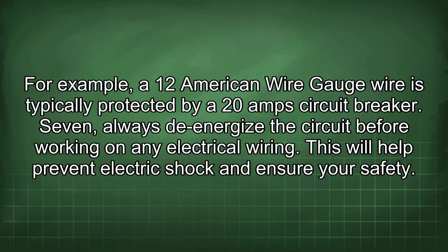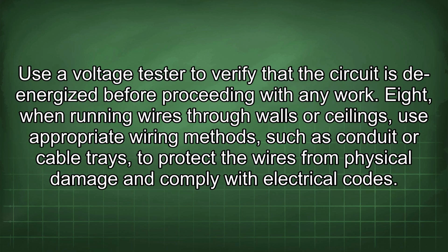7. Always de-energize the circuit before working on any electrical wiring. This will help prevent electric shock and ensure your safety. Use a voltage tester to verify that the circuit is de-energized before proceeding with any work.